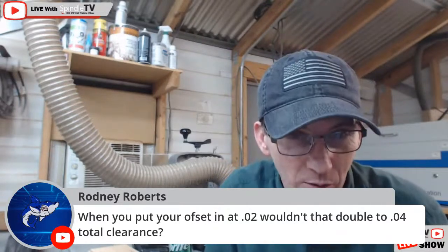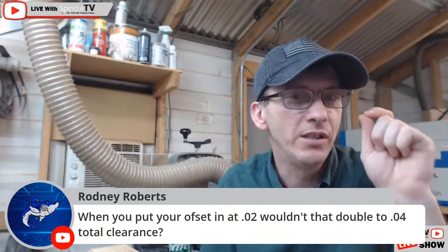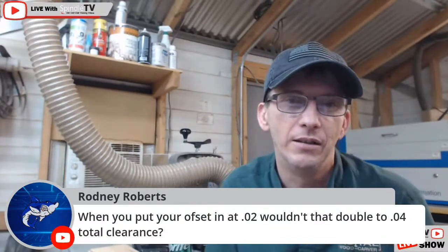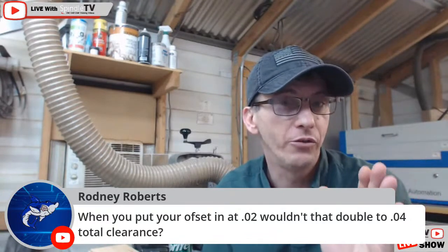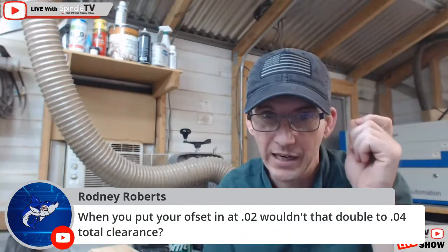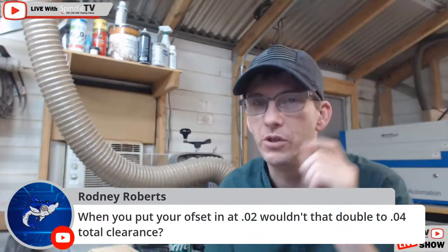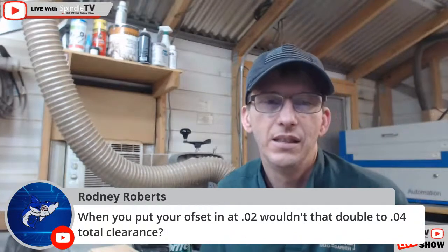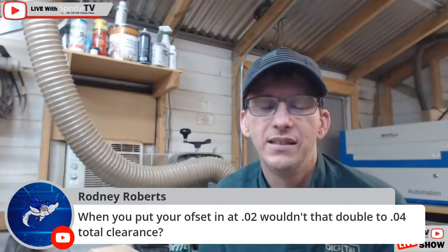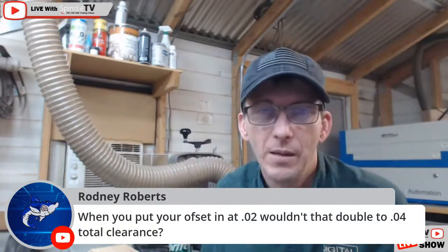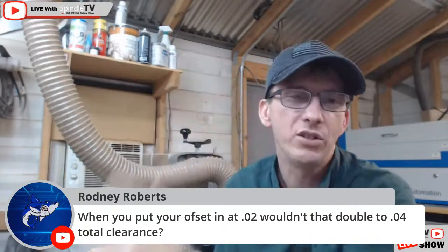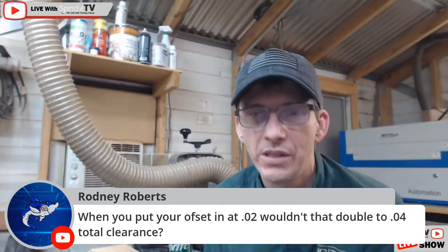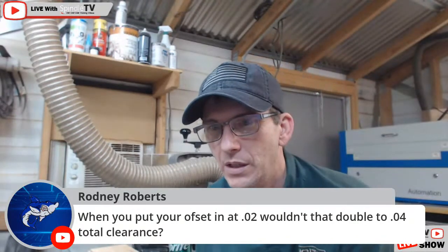It wasn't 0.02, it was 0.002, 2,000ths of an inch. 3,000ths of an inch is a human hair, right? Between 0.003 and 0.0034 is a human hair. I was at 0.002, which is less than a human hair. So I was only slightly relieving that a little bit for a better fit. But 0.02 would be way too much of an allowance. So negative 0.002. All right.